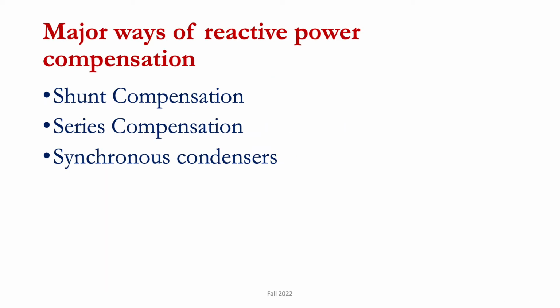Reactive power compensation can be done through different means. One such method is shunt compensation. Shunt compensation requires the use of a shunt compensator, which is a device that is installed in parallel with the transmission line. A shunt compensator is always connected in the middle of the transmission line. It can be provided by either a current source, a voltage source, or a capacitor. An ideal shunt compensator provides the reactive power to the system. Shunt-connected reactors are used to reduce line over-voltages by consuming the reactive power, while shunt-connected capacitors are used to maintain the voltage levels by compensating the reactive power through the transmission line.